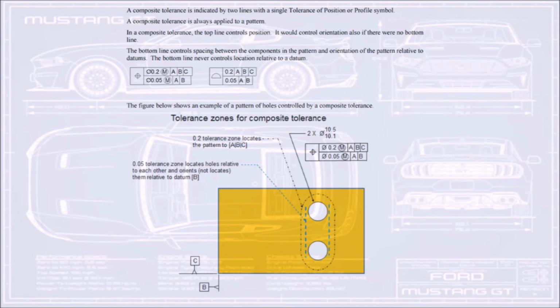A composite tolerance could specify both the diameter of the pattern of holes and the diameter of each individual hole, as in the following illustration. When you add composite tolerances to a drawing, you specify the first line of a feature control frame and then choose the same geometric characteristic symbol for the second line of the feature control frame. The geometric symbol compartment is extended over both lines. You can then create a second line of tolerance symbols.